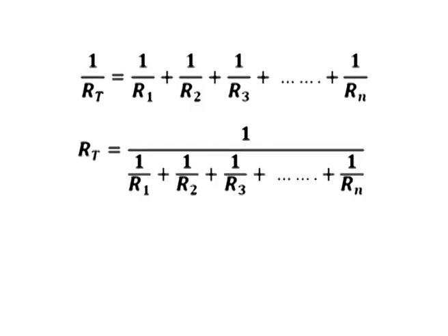The case of two resistors in parallel. The equation we deduced in the earlier section by finding the reciprocal is a general formula for finding the total resistance for any number of resistors in parallel. The combination of two resistors in parallel occurs commonly in practice. Also, any number of resistors in parallel can be broken down into pairs as an alternate way to find the RT. Based on the equation, the formula for the total resistance of two resistors in parallel is given by this equation